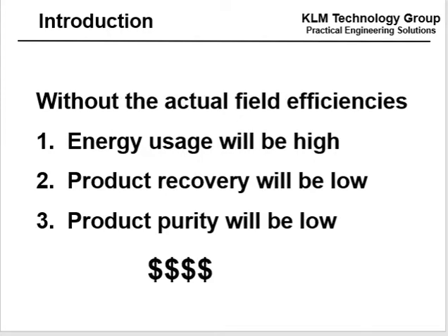Without the actual field efficiency, if your simulation is very different from what's actually in the field, energy usage may be very high, product recovery will be low, product purity will be low. You might not even make your specification. And each one of these things costs money.